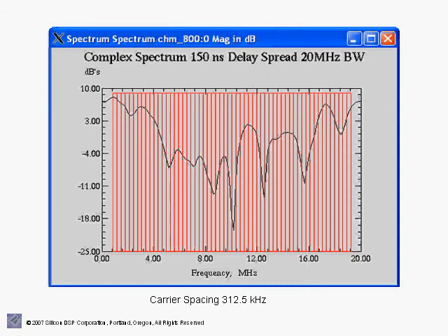We will also discuss ways for combating multipath fading channels, in particular by breaking the bandwidth into multiple sub-channels, each with a narrow bandwidth, so that for each sub-channel we have flat fading versus frequency selective fading, and how we would multiplex all the data that is transmitted in parallel, and then we will derive a bandwidth efficient technology for transmitting over multipath fading channels, in particular orthogonal frequency division multiplex.